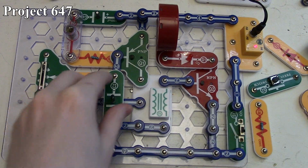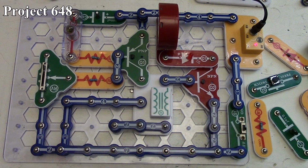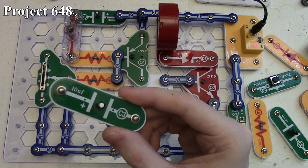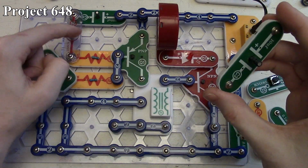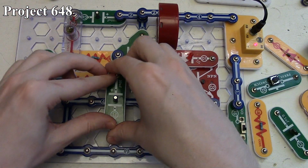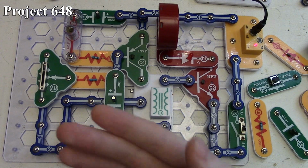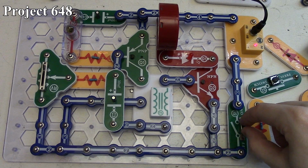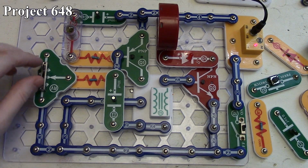And now Project 648, we're going to increase the capacitance even more. So now we're going to go up to our 10 microfarad capacitor, and these are polarized, so the plus is going to be facing toward the top because that's where our current is coming from. So as you'd expect, when we increase the capacitance on this, the circuit's going to oscillate even slower. Again, with a lower frequency as well, so you can hear the tone is not as defined as when it was oscillating faster with the smaller capacitors.